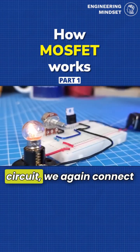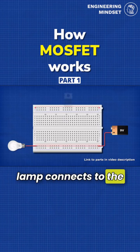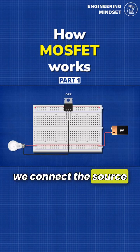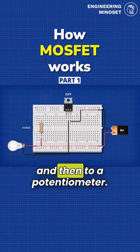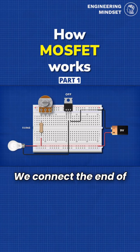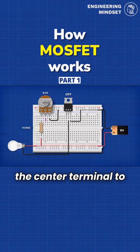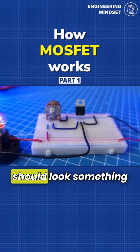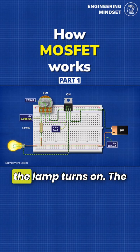For the next circuit, we again connect the 9-volt battery to the lamp, and then the lamp connects to the drain terminal. Then we connect the source to ground. Then we connect the battery to a resistor, and then to a potentiometer. We connect the end of the potentiometer to ground, and we connect the center terminal to the gate pin. The circuit should look something like this. The MOSFET will be activated, so the lamp turns on.